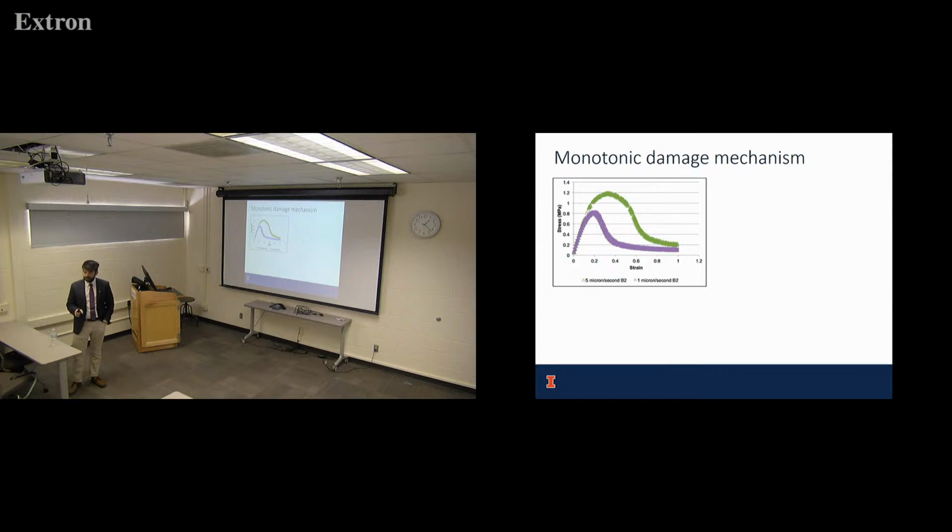That's a good point too, that the aging condition has a big influence, just like the temperature, loading rate, and triaxiality. But our theory here is that at the end of the day, a crack is a crack. We always assume PAV is going to lead to cracking, but it doesn't necessarily occur in the later stage of life. It could happen in any stage. So especially if we're going to be doing these very high rates and we want to prevent adhesion failure, we want to use the unaged binder.